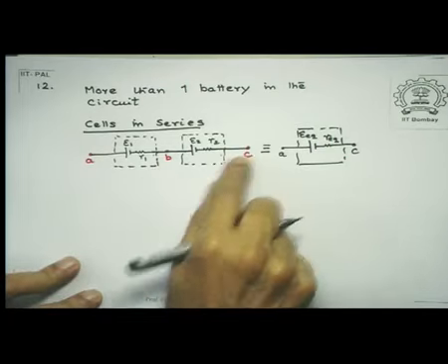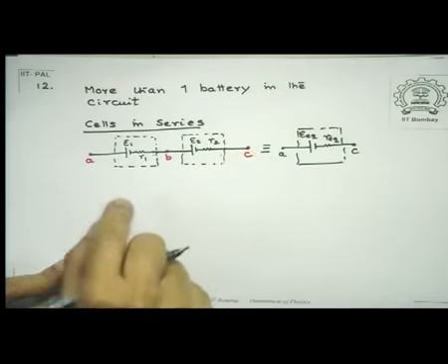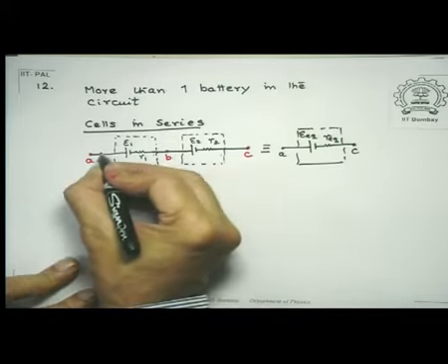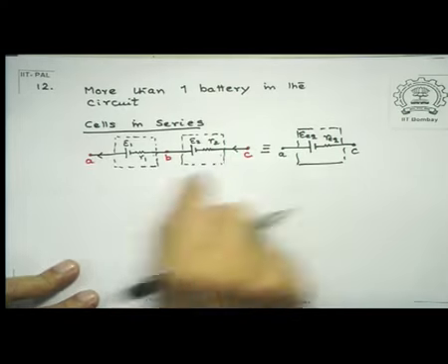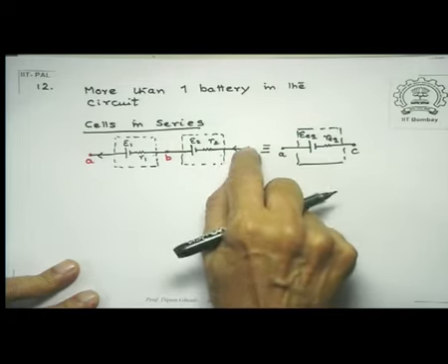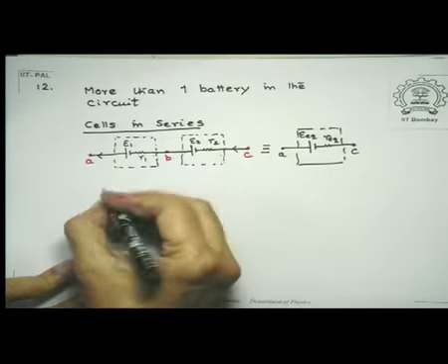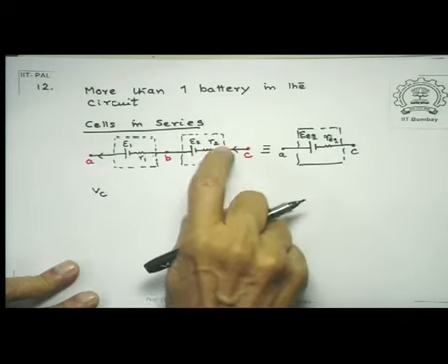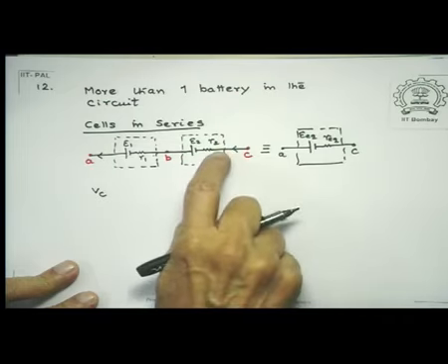Now, let us look at this. So, what is Vc? If I assume that the current is flowing like this here and is coming in like this, then I look at the way the potential develops as I go from C to A. So I start with Vc. Since this is in the direction of current, I have a drop of IR2.